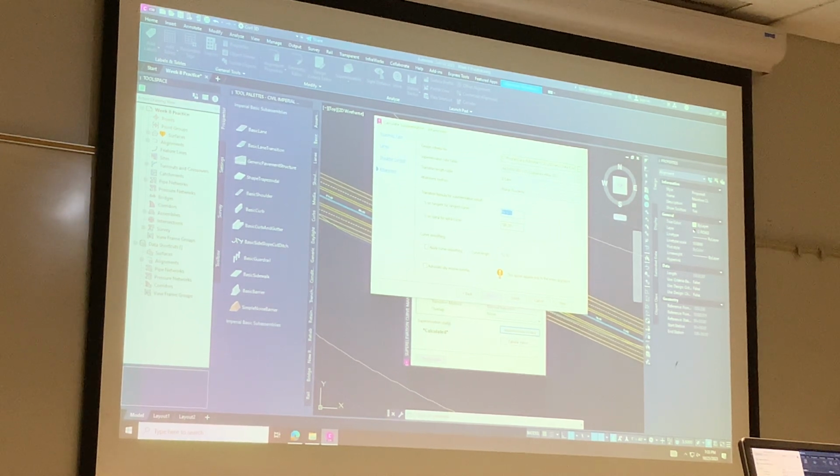In this final window, we didn't change anything, we just checked to make sure it's using the right super elevation Emax chart. It's telling us it's going to use a 10% chart.